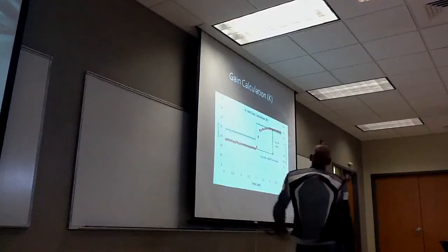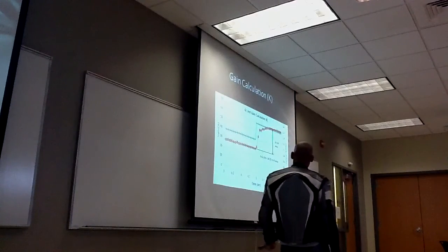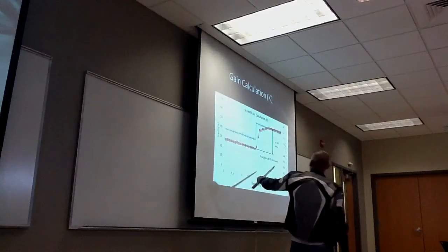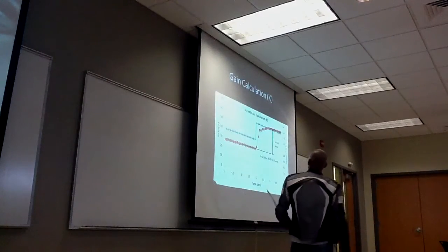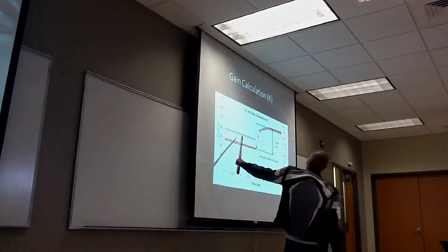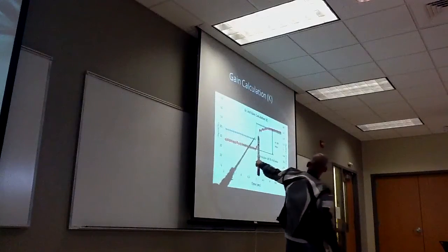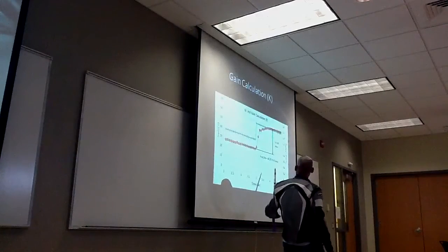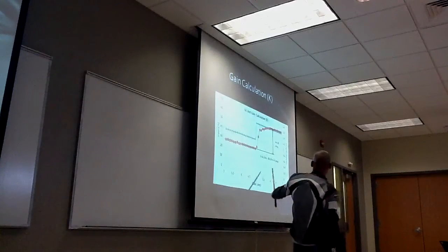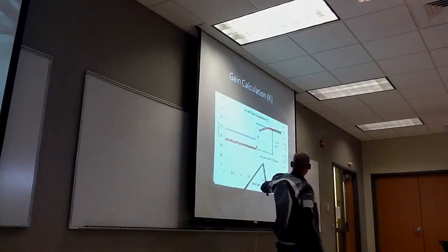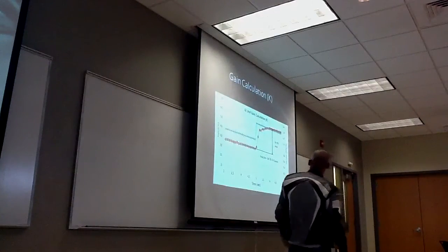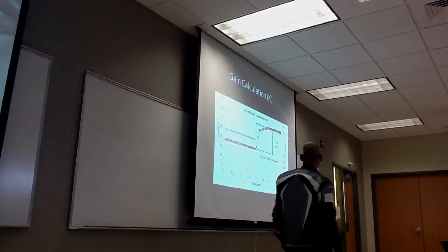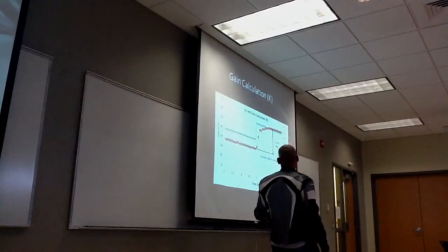You take the difference between those two, and you get the delta C. And delta M is basically the range of the input, the lower input to the upper input. Then you set up the equation, delta C over delta M, which gives you your gain. For this particular graph, you get 0.43 amps out of it.